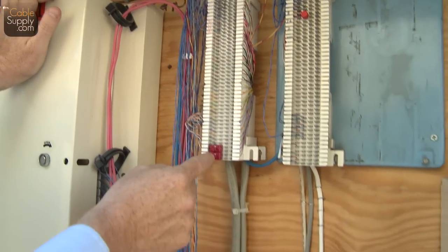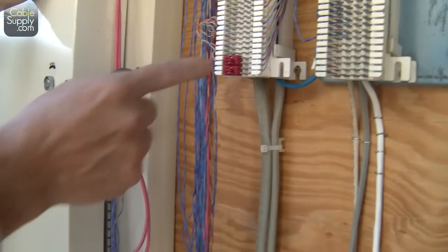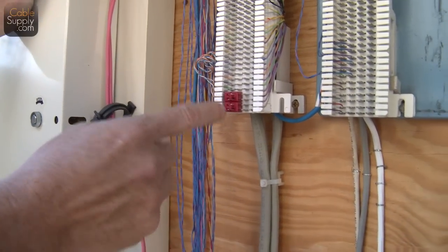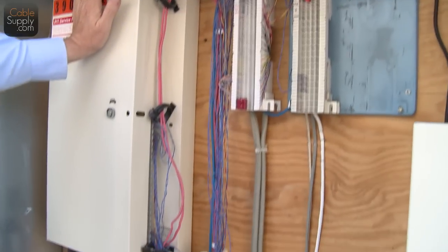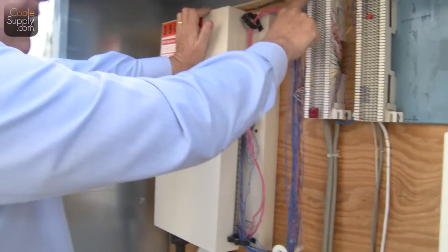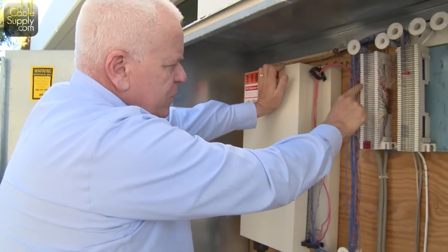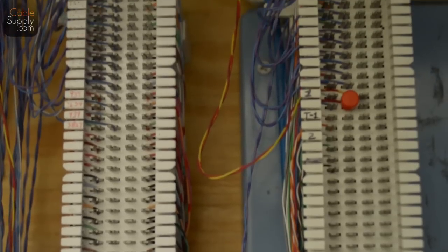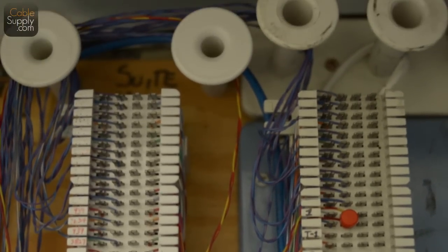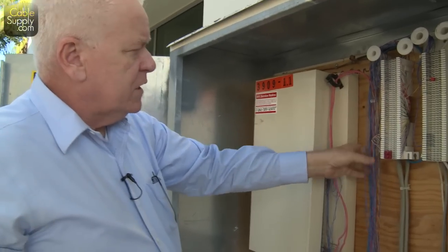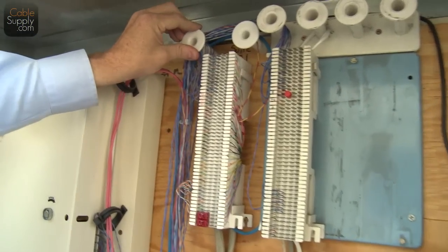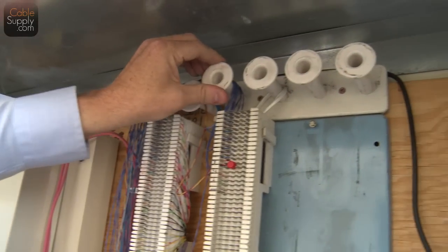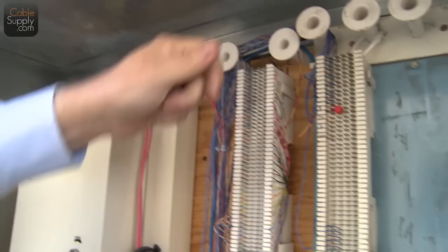Now this signifies a special circuit, usually a T1 or a PRI, so I don't mess with that. Same thing over here. But these are your CO lines, your basic CO lines. And a lot of times it's written right here, and it looks a little faded, but some of them are written in there so you can see them. And the reason why these things have loops in them, this is a proper way to do it. You keep them loose and you put the loops in them. At the same time, you put these things up here called mushrooms, and they hold the cable.